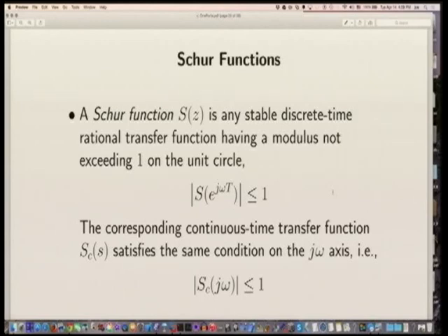If there's no damping, they'll be all-pass, but in the more general case, they'll be Schur. So there'll be some attenuation or unit gain at every frequency, never greater than 1. So passive impedances have Schur reflectances.